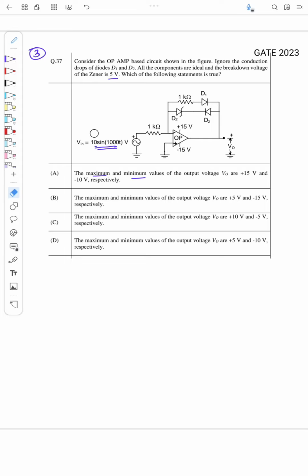Okay, so I have a sinusoidal input here. Say because of this, V0 is positive and having a higher value, some large magnitude of V0, or the maximum value of V0 is there. So what happens if this node is plus? Then diode D2 is on and diode D1 is off, right? So I can say it's like an open circuit, and since it is ideal, it is completely connected, right? This is like a closed switch.